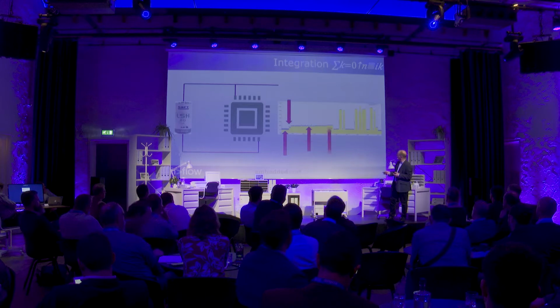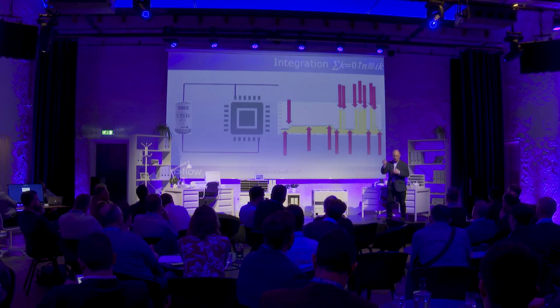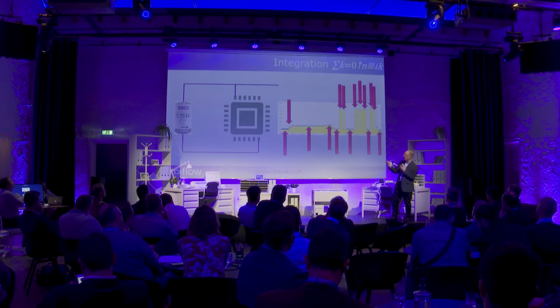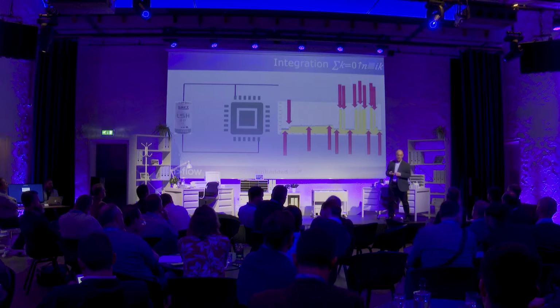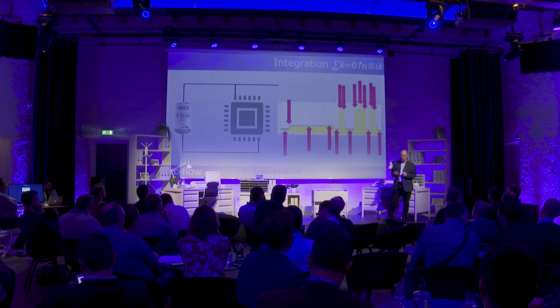But of course, it's a bit harder than that, because we've got all of these different modes that the microcontroller is running in, different frequencies it's running at, different peripherals turned on, which are really dynamically affecting the current consumption. And we have to work out the area under the curve for all of that chart. It's a minefield and practically impossible to get right.